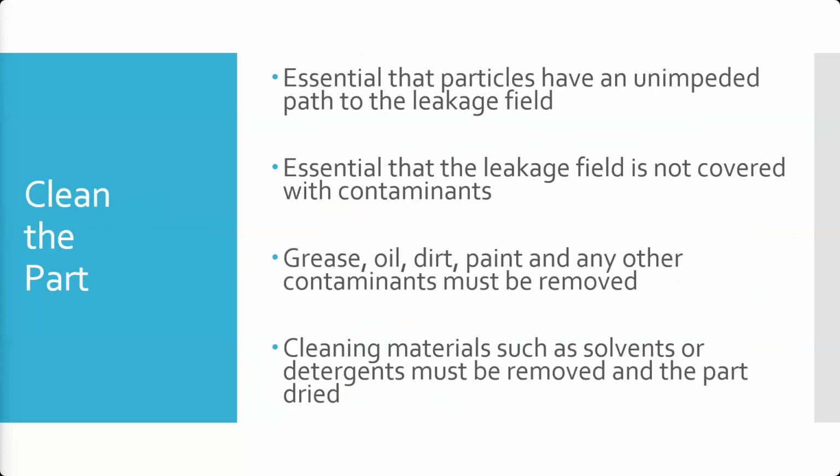So cleaning the part, it's essential that our particles have unimpeded access to the flux field that is leaking from the surface of the part. And so in order to do that, we got to make sure that there's no contamination on the surface. We don't want a bunch of grease or oil, the grease and oil can get sticky, having the particles get all stuck in that stuff, right? We also don't want it to be thick enough.